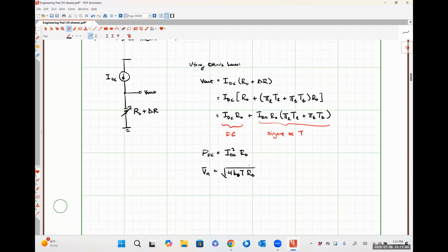And that could be problematic because depending on what our headroom requirements are, if our DC signal is a few volts, we're still just boosting things up when we might wind up with a saturated signal at the output of our amplifier. So it could be problematic if the DC level on this thing is too high.